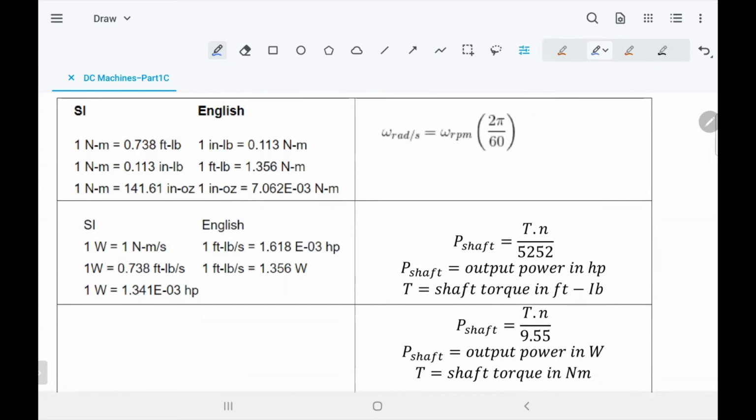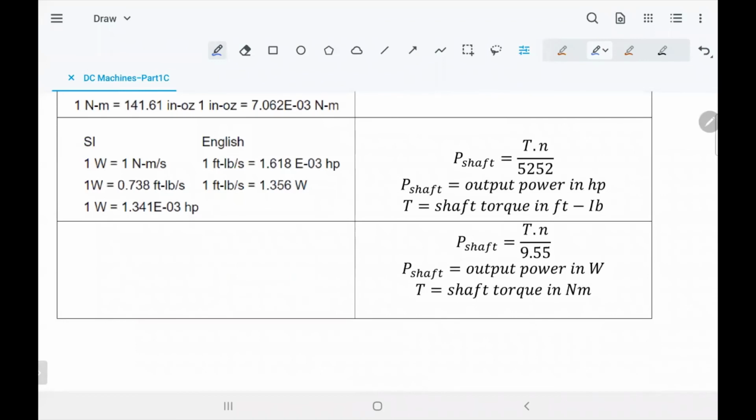These are the units that I will keep in the folio. It's very important, the unit to use, because not everybody uses the torque in Newton meter. Maybe in Europe they do that. They do also here, but sometimes you use foot pound. So I give you here the conversion when you need it. And also, usually the DC machine, the DC motor, they put the power on the nameplate. And the power, usually if anything is moving, rotating, they give it in horsepower. So to solve or to analyze things, you have to be able to convert from horsepower to watt. So 1 horsepower is equal to 746 or 747 watt. I put also the information here for the horsepower and the watt. That's the relationship given.